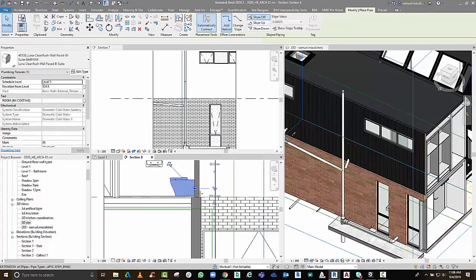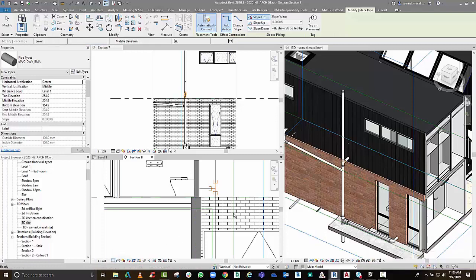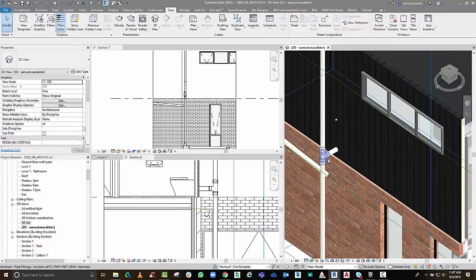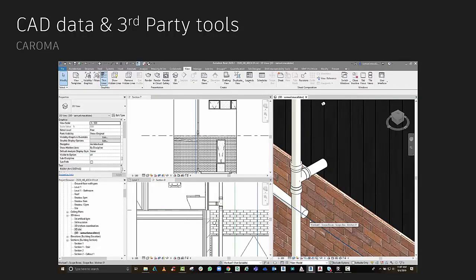Inside of that section view, you can see there is a pipe, and because I've got certain types of families embedded in the model, this will connect up and add the fitting. So you can see I've done it in 2D in the elevation view, but it's also showing up in the 3D view. So by just going to these third-party sites and downloading these files, you can load them into your model and then connect them up to your supply and drainage services.